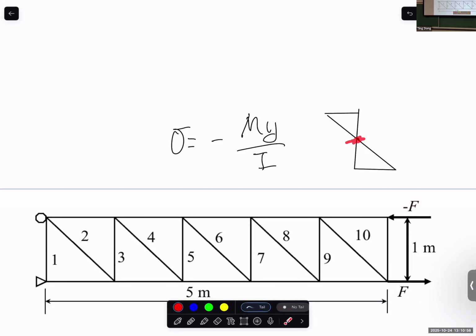Normal stress equals 0. On top of the surface is the maximum, but it's compressive stress. At the bottom surface is the maximum magnitude and it's tensile. Makes sense or not? Because let's say it's bending in this way. So this is how the stress should change in the structure.